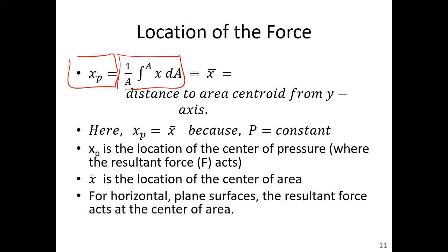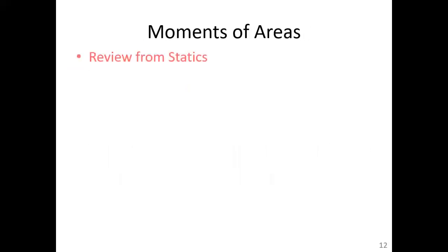Okay, so for a horizontal surface, the resultant force acts at the center of area. The center of pressure is at the center of area. And again, just to be completely redundant and boring, that's for a horizontal surface. Now, this is the review from statics.